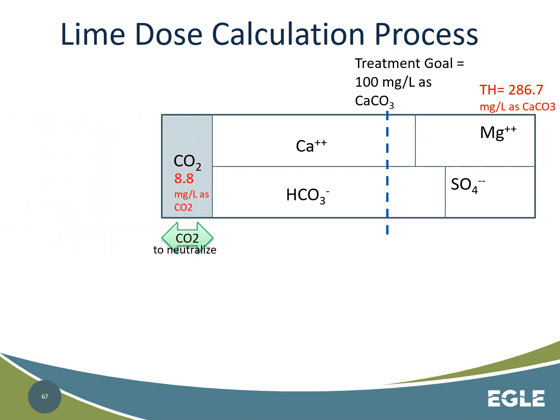We know we need to neutralize the CO2, and we know that the calculation for that requires that our concentration of CO2 be in milligrams per liter as CO2. So that's what we've shown here.